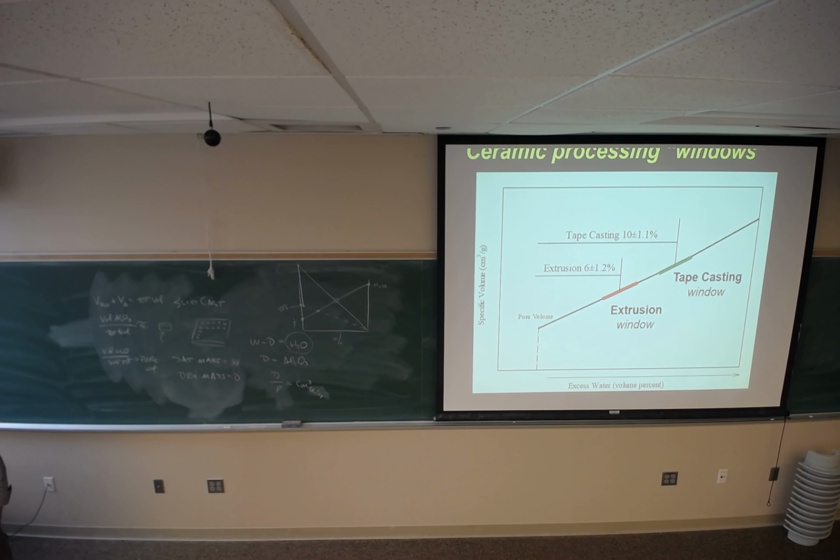The mass of the water decreases, which affects your total volume. Your total volume appears to be smaller. You then estimate a higher density for your packing efficiency than you actually have. That screws up your pore volume. I would think one of the experiments you might do is to determine how sensitive this test is to time after casting. You understand?